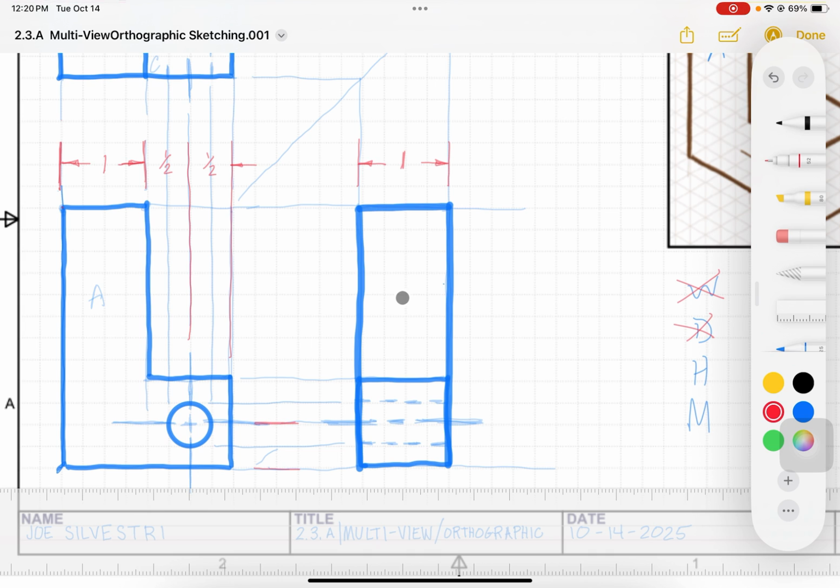Okay, so my center line was a little bit long, and so maybe if I go in and just clean that up a little bit, something like that. Okay, so I have that little bit of a gap there. My center line does not end on the object line. We can't have that, but we do have that little gap in here. And quite honestly, if you actually connected that like this and over here on this guy as well, that's fine too. You can do it either way. Okay, this can just be an extension and extends out.